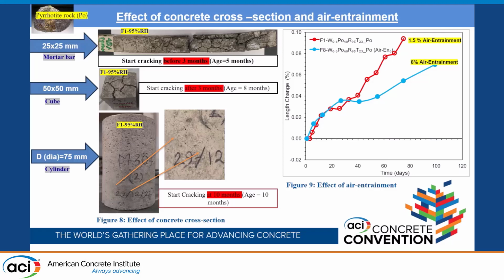Figure 9 shows the effect of air entrainment. With the increase of air entrainment, the expansion is decreasing. It could be because with air entrainment, the permeability of concrete decreases.